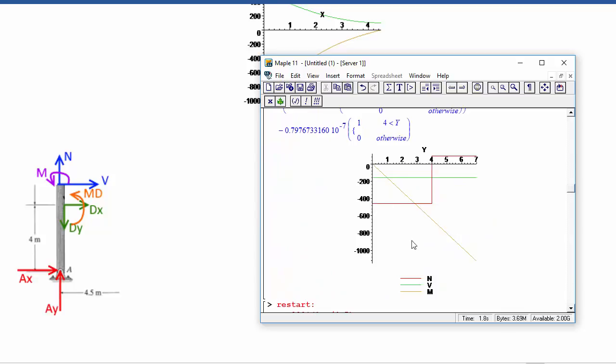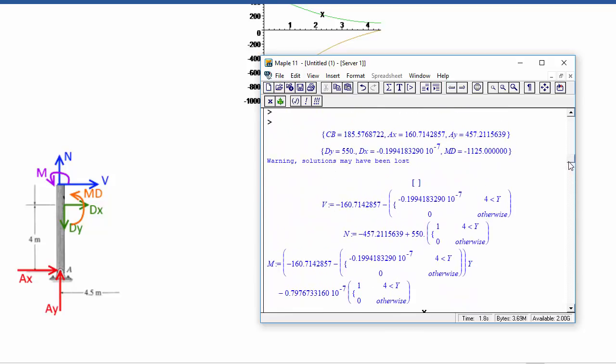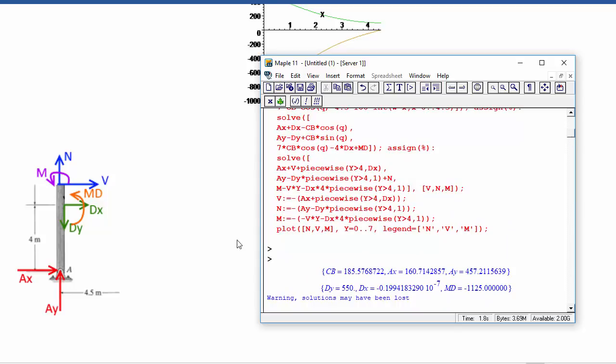Now at the top, this should be limiting to a moment of 0. So it seems like something has gone wrong right away. When we're at a y of 0, we should have a moment of 0, and when we're all the way at the top, there's no torque, there's no point torque applied at the top, so that should also be going to 0. So let's see exactly what went wrong with the torque expression.